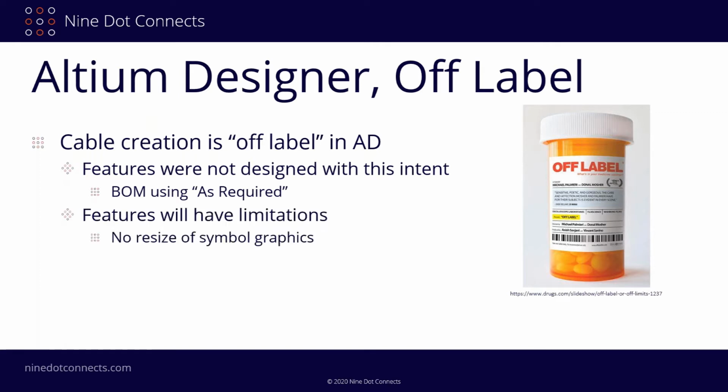One of the big ones you're going to see here today is that we cannot resize simple graphics, which would be really great in certain instances. But once you draw something with line primitives and polylines and curves and so on and so forth in the schematic library tool, once you bring it to the schematic side, well, guess what? It's fixed in place. And they give you a little bit of leeway with the pins that you'll see, but generally speaking, any other primitive you use, they are fixed in place. So we have to work around this concept.